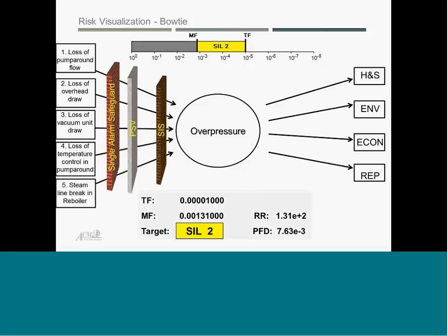And that SIF leads to the next question: do we need that SIF? And the answer is obviously yes, because we still have color in our LOPA graph. We could add in a whole bunch of safeguards to cover a SIL2 gap, but that's pretty hard to do, and that's represented by the yellow. If it was a little lower, it would be blue, showing that you could cover it theoretically.